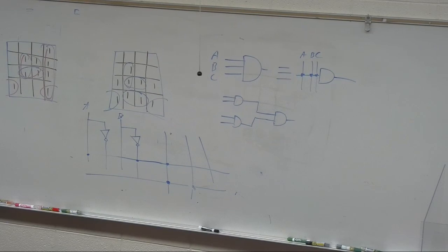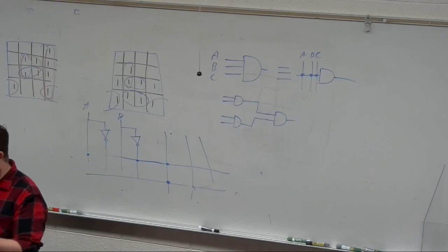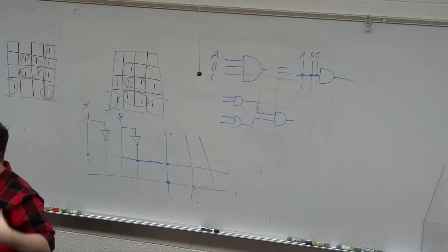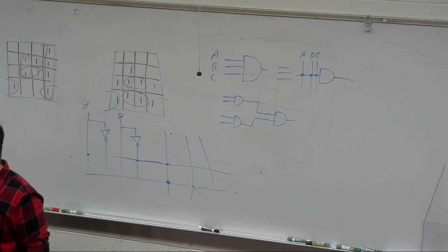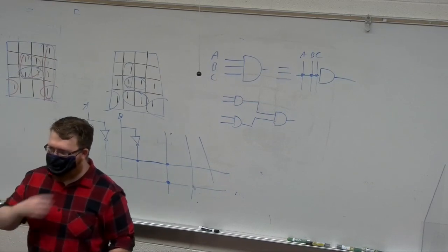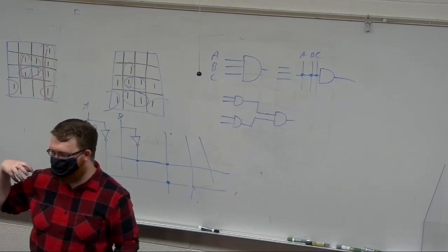I think it might be confused. Try creating a project that doesn't have top VHD in the project. There's a terminology intrinsic to both VHDL and Verilog where if something is named top VHD, it assumes that it's the top level and that's what it wants to work with, and everything else is ancillary to that. So maybe you can just remove top.vhd from the project and just run it on the component. I think it's getting confused because it appears to be pulling nets from top VHD, which you don't care about.